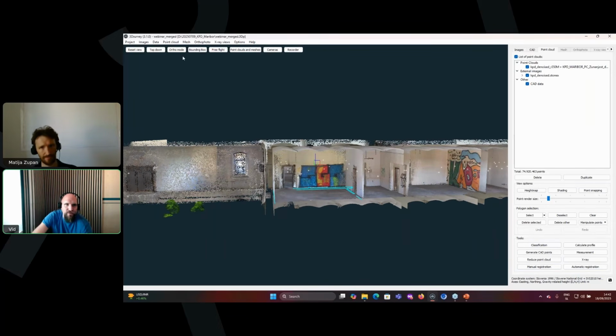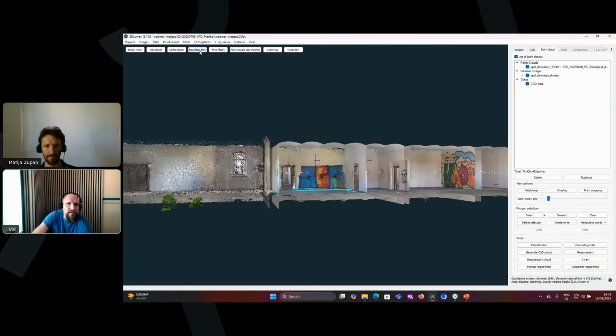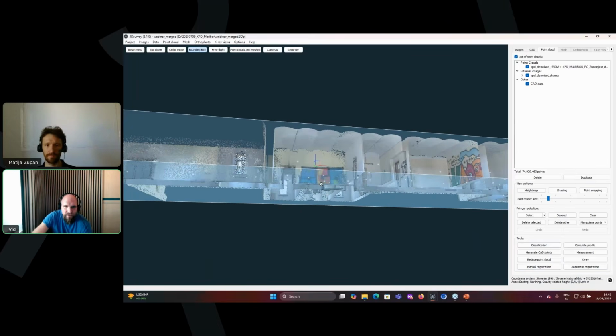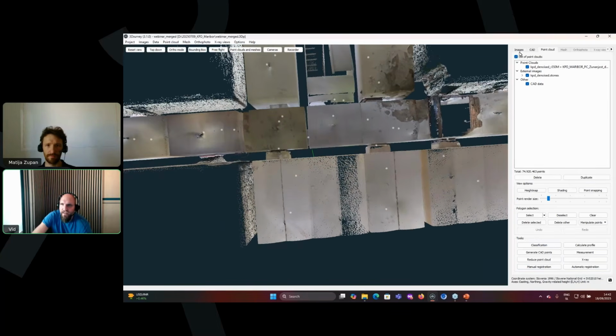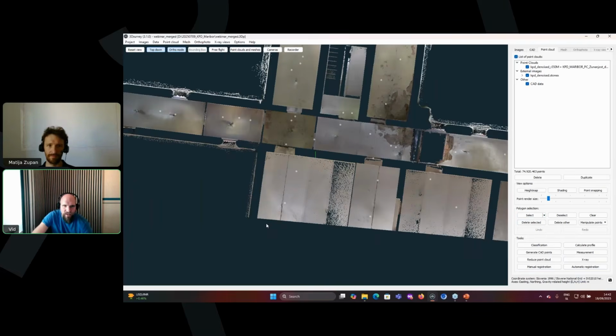There is a neat trick that allows you to calculate an average height of this kind of roof model. So we'll achieve that by moving the bounding box up here. Then they went in and selected the points inside of this roof section, like that. Before I do that, I should press escape and go into top-down and ortho mode, so that when I do the selection, I only select points within my polygon.